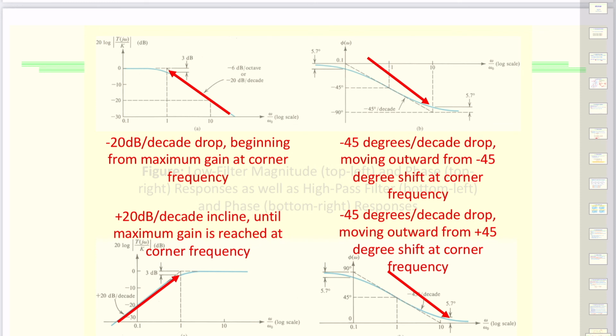We also define the cutoff of the bandwidth by using the 3 dB points where the signal amplification reduces by 3 dB, and we take that as the cutoff for that STC network or circuit.